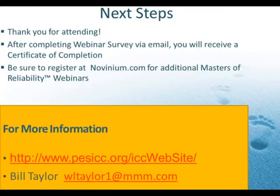Otherwise, it could be floating, which would be bad, because then it would float up with voltage on it. It's important to have it at ground potential, and also to bleed off that same leakage current that's coming out of that system. So very, very important either way, and either way can lead to failures if the housings aren't grounded. Okay, thanks.